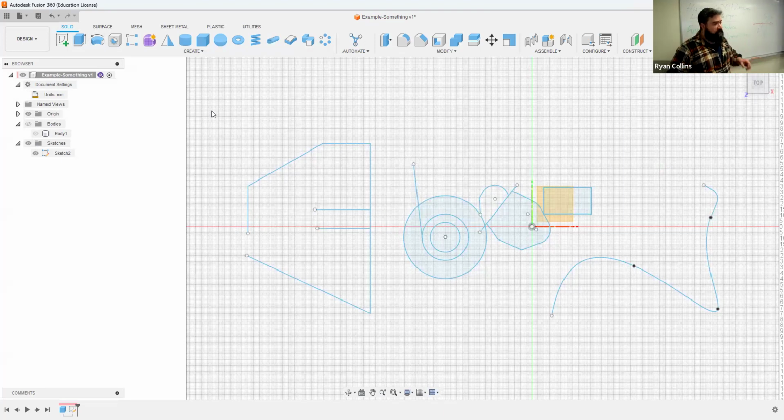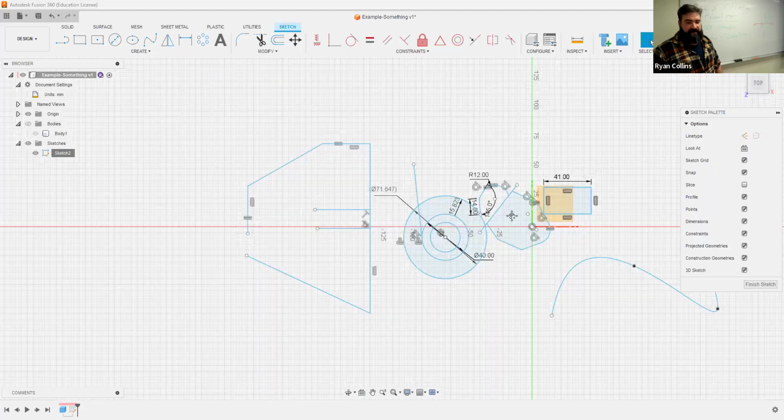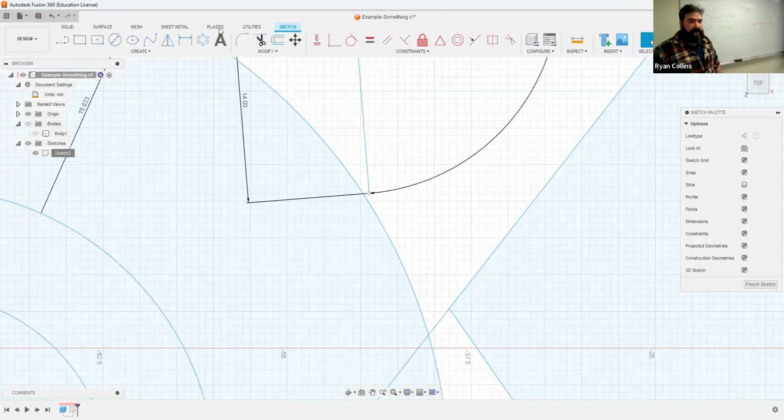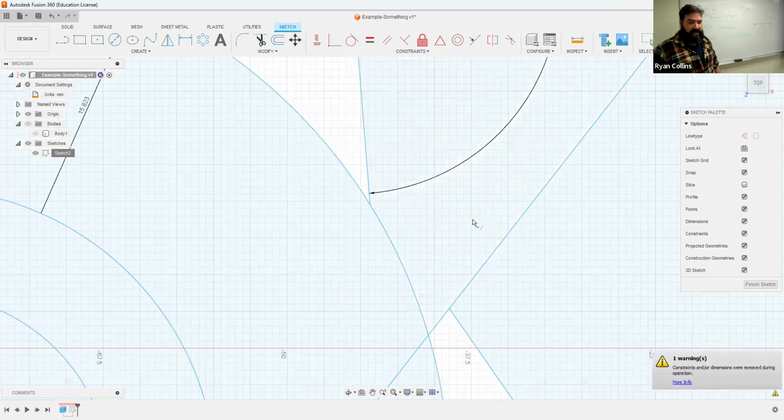Now, if you are drawing something that you are going to extrude, it all needs to be on the same sketch. But if you're going to make different levels and things like that, it could be different sketches. What I mean by that is, you see all these closed sketches, meaning they're light blue inside. The ones that are not light blue, if I wanted to extrude those, I need to close that sketch. In order to do that, you need to go back and alter your sketch. So either right-click on the time slider object, or over here, right-click, just go to Edit Sketch, brings you right back. The reason this isn't blue is because that's not touching. I could use the Extend tool, and now it closes that. There you go.